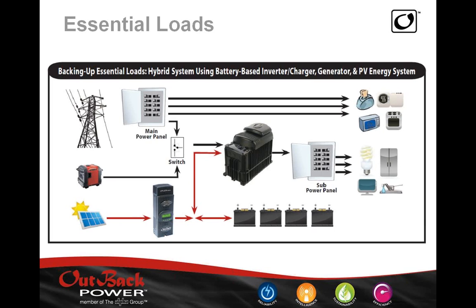If the batteries are fully charged, everything that's being harvested will basically be going to the loads. And if the grid fails, the inverter then switches from the grid to the batteries. If the failure happens at night, then we have the batteries as a source. And if it happens during the day, then we have both the PV modules and the batteries.